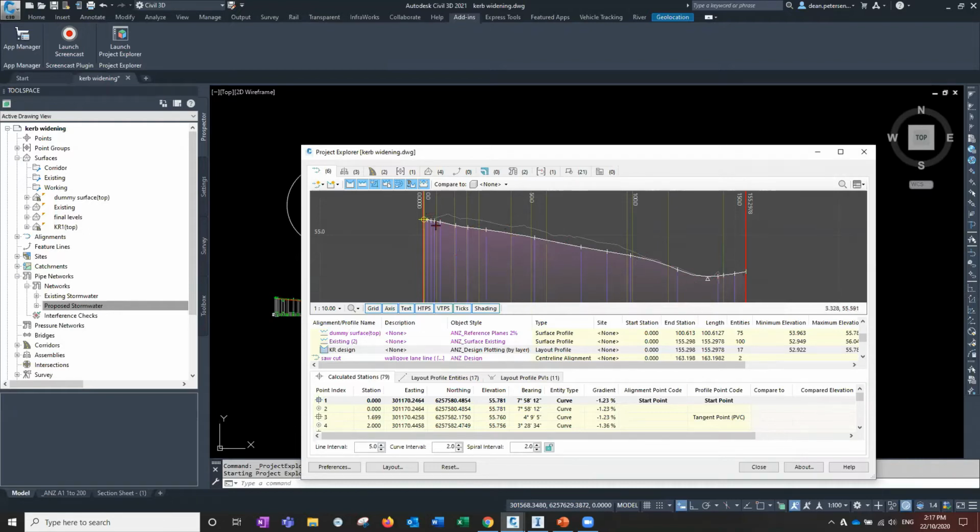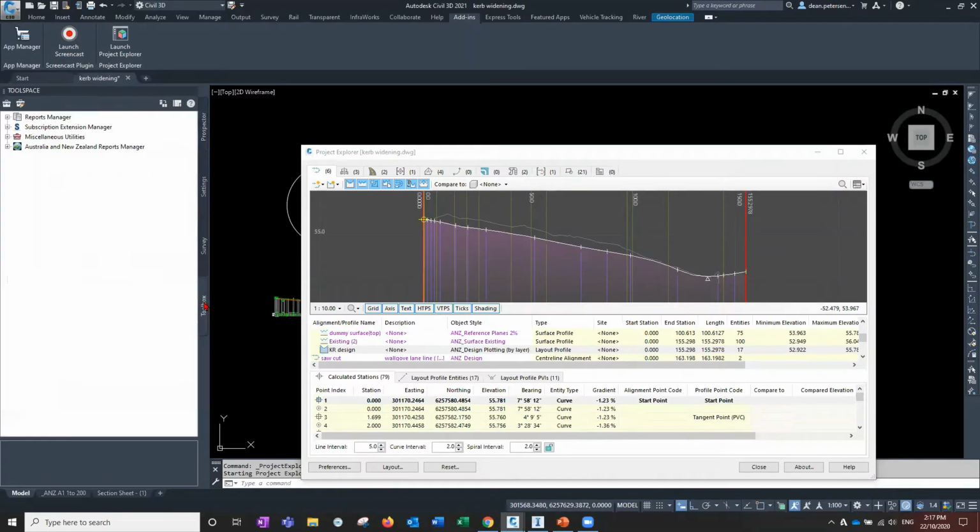You might want also to have certain locations along that profile reported out. So where the changes in straights and curves occurs, where the low points are, for instance, you might want values in the report at those particular locations and get it all out in Excel format. Now, it was difficult to do before because in Civil 3D, we only had this thing called a toolbox, which was pretty much non-customizable.